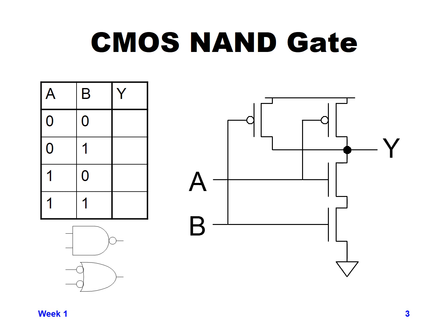So let's go through the logic quickly. In this particular case, if we have A and B both 0, that means both of the PMOS devices are turned on. Both of the NMOS devices are switches that are off. That means you have two different connections up to VCC. You have no connection down to ground, and you will get a 1 value out for 0 and 0 in.